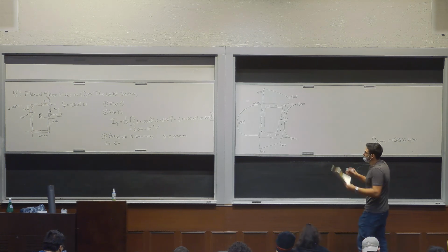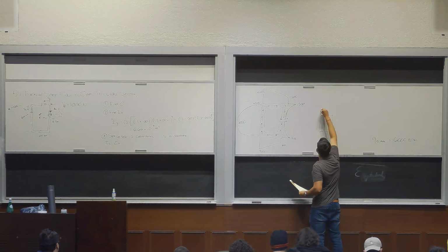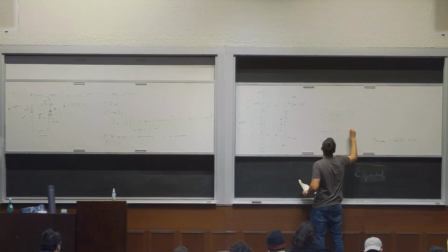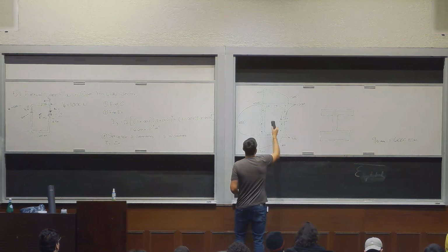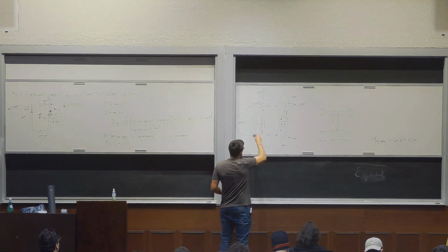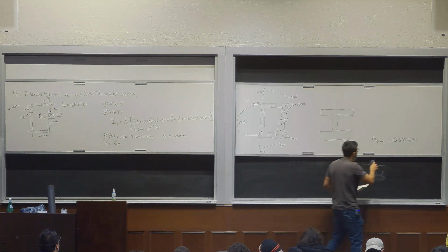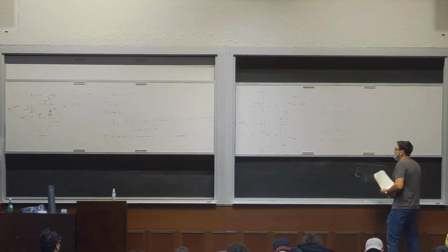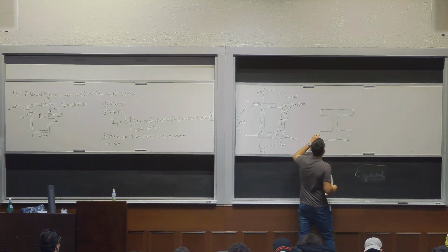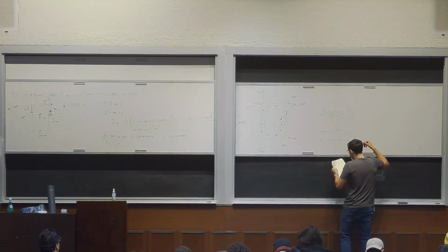Okay, so that's for that cross section. This thing I mentioned about starting at any open location, right? It's not super beneficial for here, because we could have just taken it progressively from here to there to there to there, and just keep adding these terms. However, for other types of cross sections, for example, this I-beam looking thing, there's a bunch of open starting points. Okay, so let's say we have some VZ acting on it.